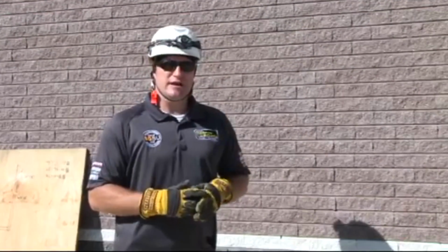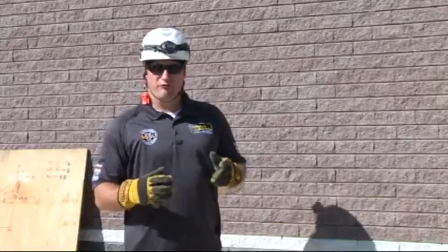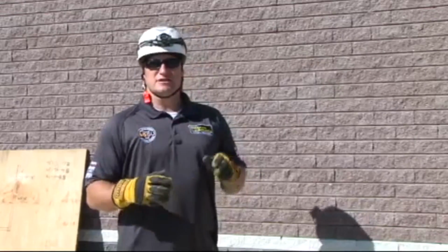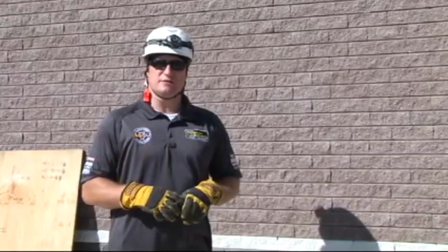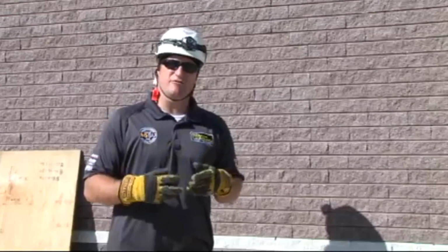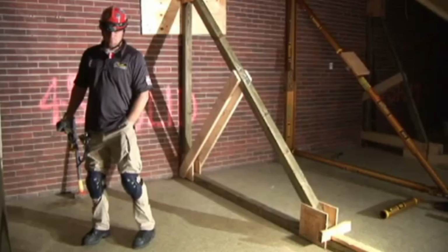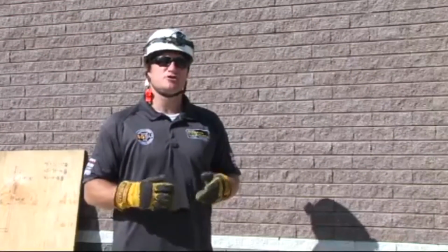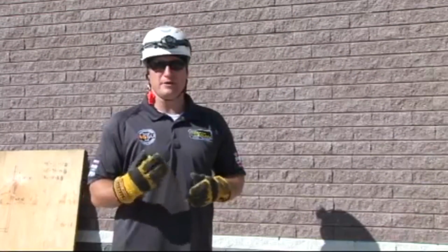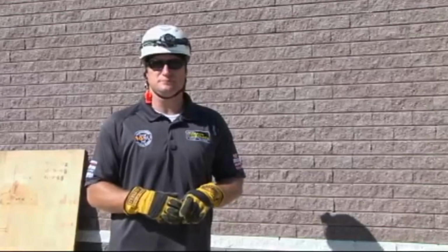Another good indication we can be aware of before we even start fabricating is some of the determining factors or the cutoffs with raker design. If a raker itself is greater than 11 feet in length, we know that we're going to need midpoint bracing. With an 8-foot insertion point, you're going to be at 11 foot 3 inches, so we can already start pre-planning for that midpoint bracing and establishing that.